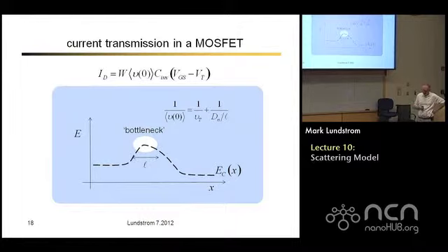So you sometimes see in textbooks that under high bias, the current in a MOSFET is a drift current. But I don't agree. I think it's a diffusion current. You diffuse across this thin bottleneck region. In fact, this device looks just like a bipolar transistor. We get back to that old paper in '73 by Ed Johnson. It said that these are really the same devices.